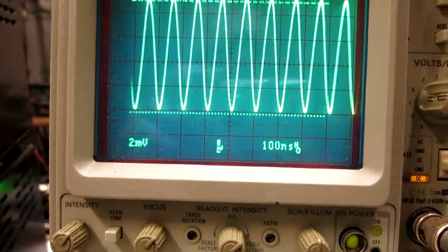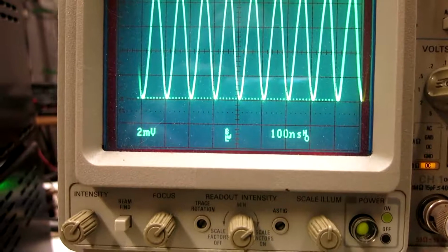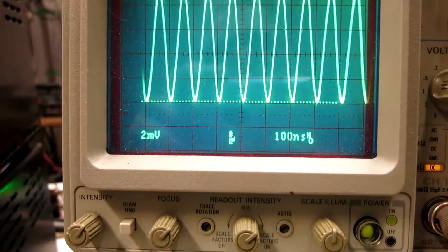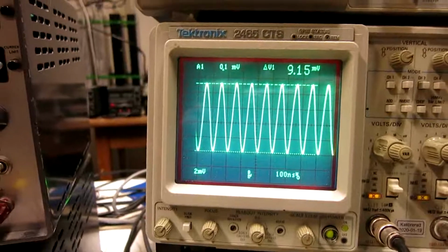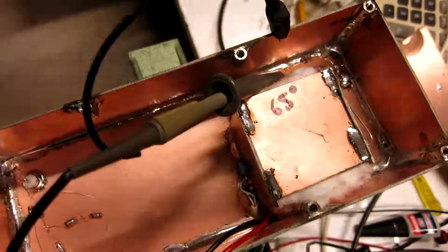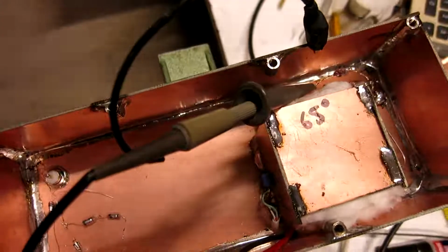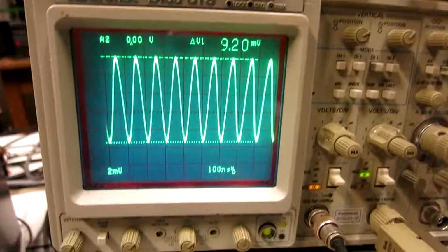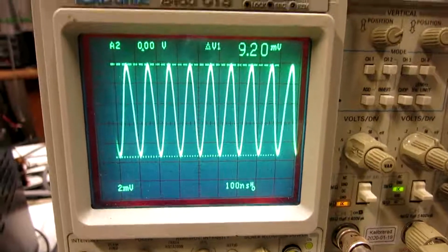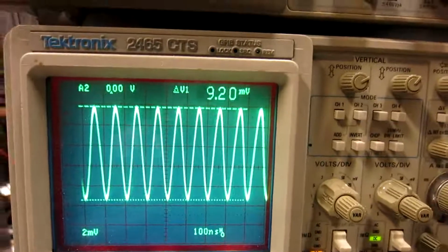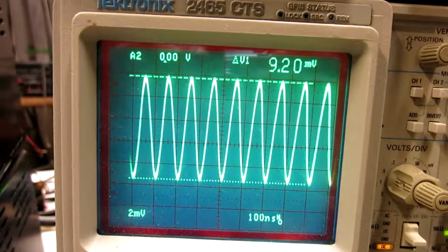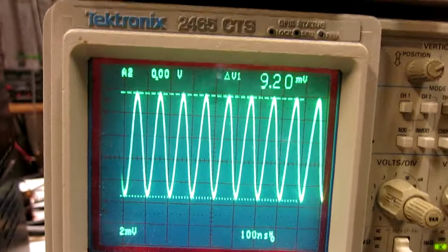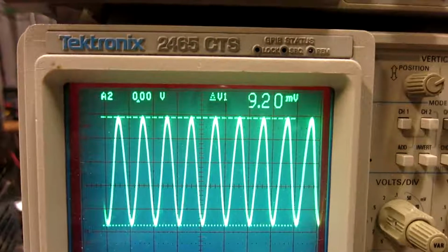Well, the oscilloscope is drifting a little bit, but it seems, well, 9.2 millivolts. I have connected the oscilloscope probe across the crystal. And then I'm looking at the monitor output, and I have set the signal level to the same 9.2 millivolts. And of course I need quite a lot of more power to do this, because there are losses in the probe.